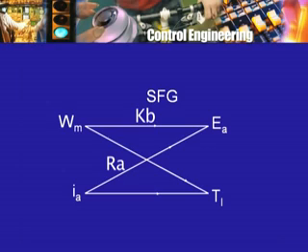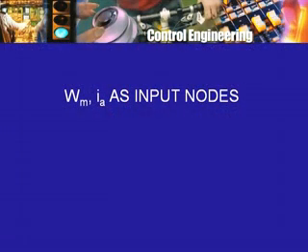That is straightforward. The second one requires you to transpose the term TL on one side and the other two terms on the other side, but that is also pretty easy. So, TL equals the generated torque, which is KT into IA, minus the frictional torque, so minus KF into omega m. So, here is the complete signal flow graph which represents the two equations in which we have armature voltage EA and the load torque TL as two nodes which are not input nodes because they have incoming arrows, whereas omega m and IA are the two nodes which are input nodes because they have only outgoing arrows.